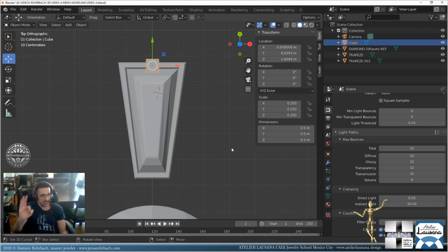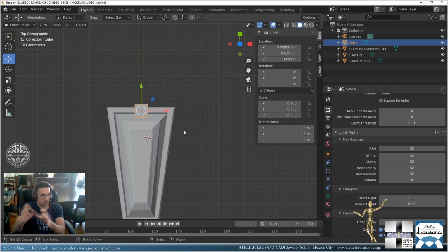That's the most recommended thickness for everything jewelry, 3D printed, and casting. Because casting, because mold, because resin, because printing, because jewelry, basically. So stick to 0.5 millimeters and you shall be fine your entire career.